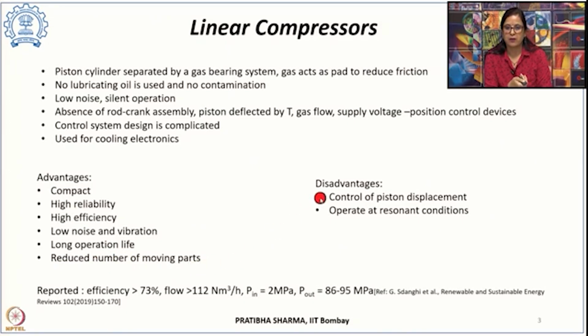but at the same time there are disadvantages also: you have to control the piston displacement, because that could be governed by various other parameters like the temperature, gas flow and supply voltage. So the controlling devices need to be integrated, and that increases the complexity. At the same time, it has to operate under resonant conditions, so synchronization is essential.